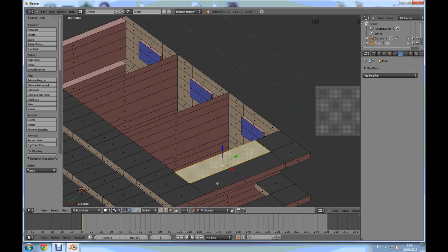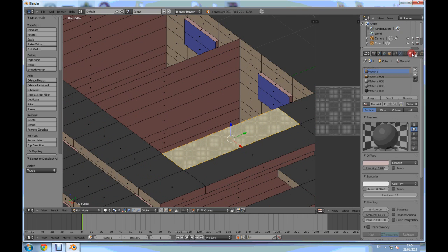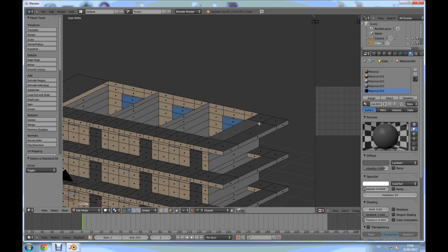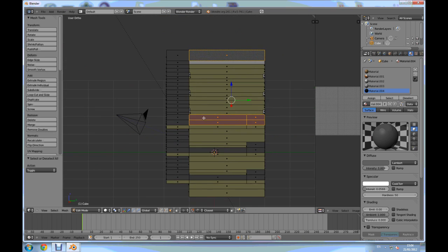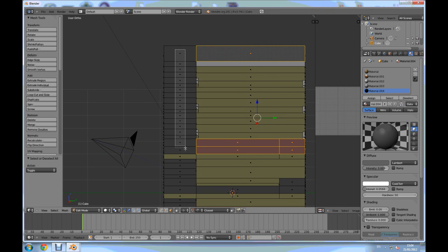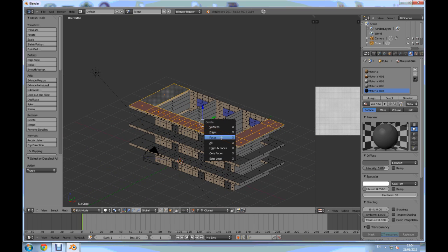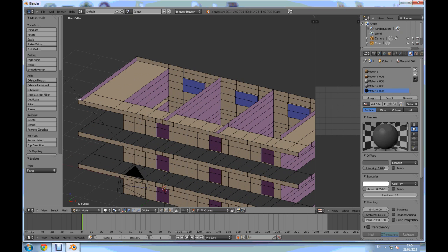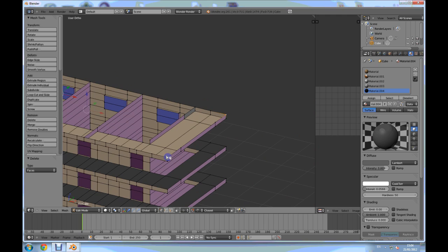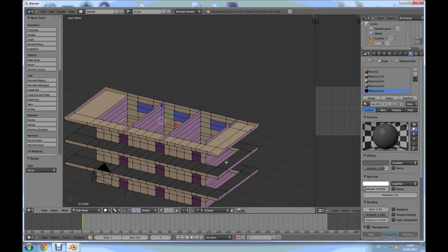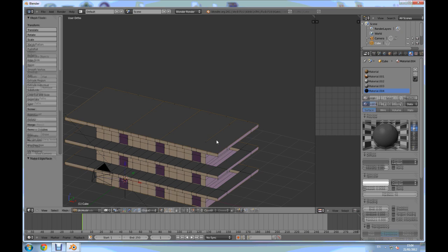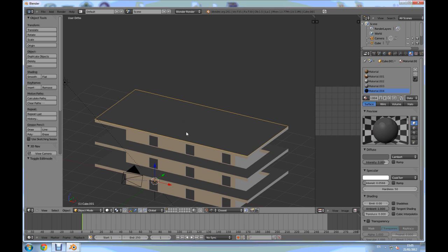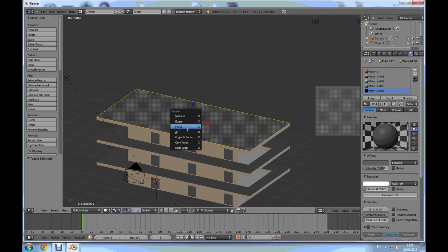But anyways, we need to change this. So select this face, go to materials, hit the dark material and press assign. Okay, just to show you how it's done. But now we'll delete them anyways. B for box selection and X, delete faces. Go to vertex selection, select the corner for 4 vertices and press Shift D, F to fill, and P to separate selection. Go to object mode, select the newly created plane, tap to edit mode, press X, delete only faces.